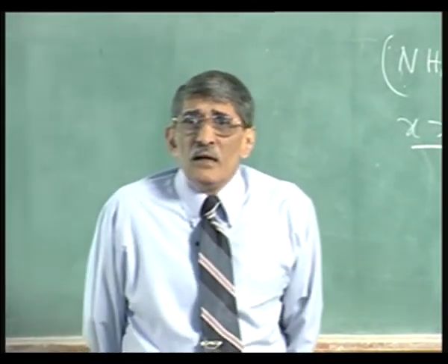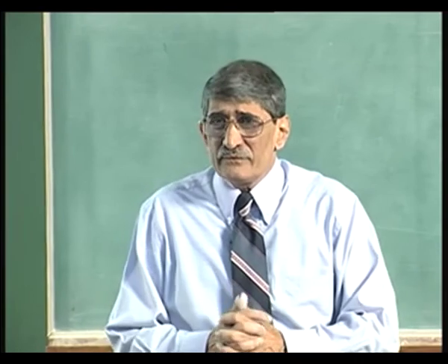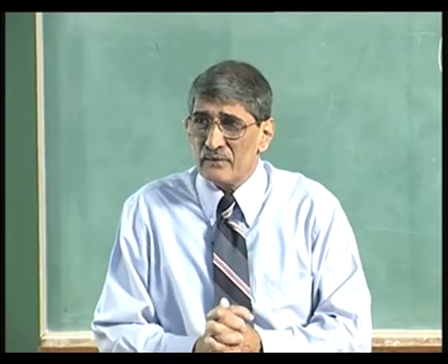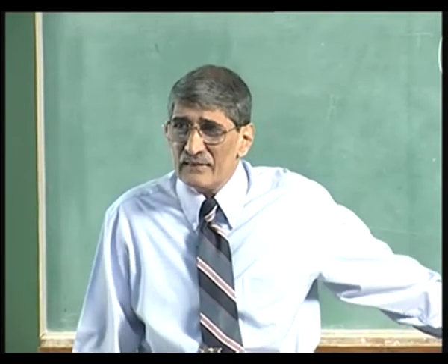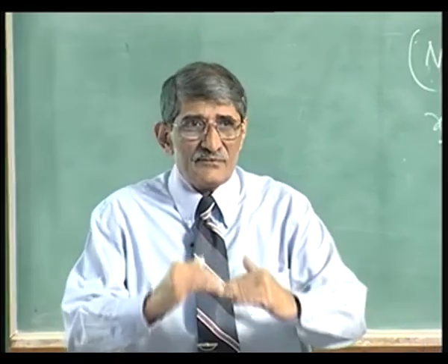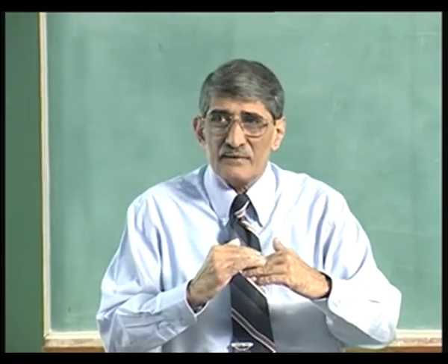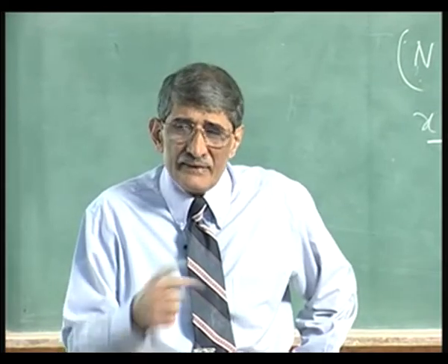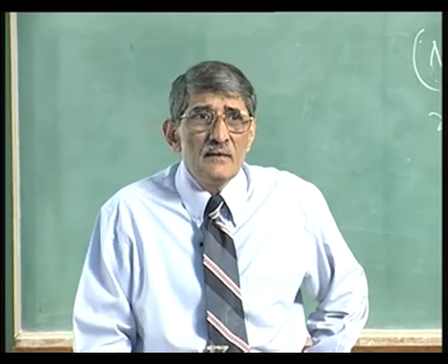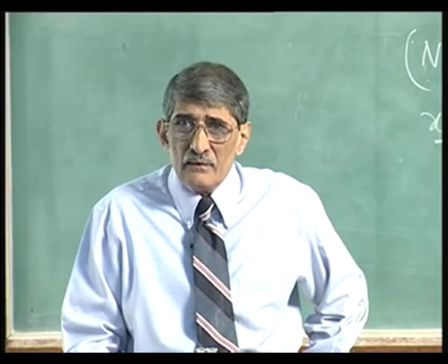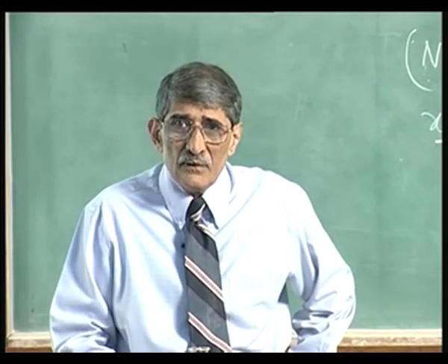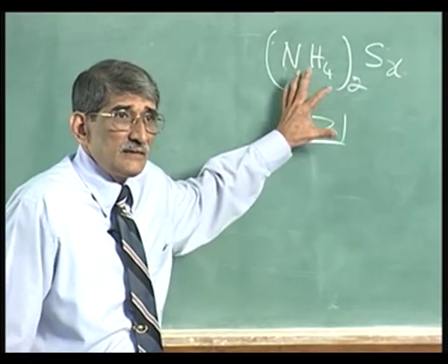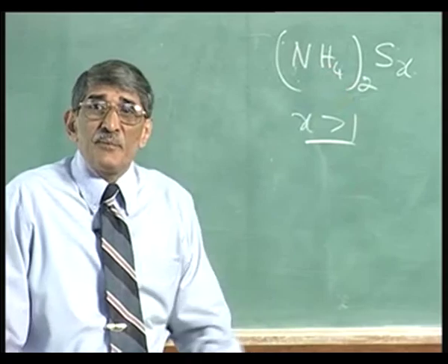Okay. This was fairly good, but even then the stability problems appeared, because this is a thin layer put there, covering the gallium arsenide layer. You need further protection. In fact, this is where we did a lot of work at IIT in the microelectronics laboratory, as part of one PhD program, where extensive studies of ammonium sulphide treatment were done, and deposited PECVD nitride.